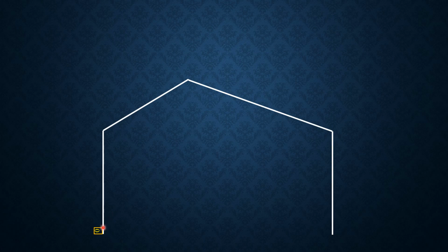So remember, for this fixed end with zero distribution factor, this one, negative 1 over 6 divided by, this is 1 over 5, the stiffness. So negative 1 over 6 divided by 1 over 6 plus 1 over 5, negative 5 over 11. So this is negative 6 over 11. While this one is 1 over 7.8, this is 1 over 5. So that's why the stiffness is 1 over 5, negative 1 over 5 divided by 1 over 5 plus 1 over 7.8.